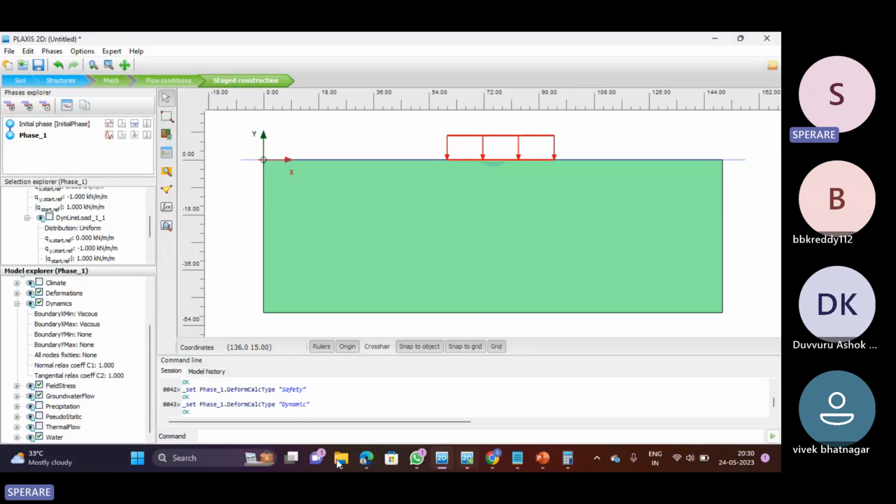If you go over here, in this particular image, because of the vibrations, a vibration is coming and hitting my Y minimum, and after hitting it, the vibration can reflect back. Why will it reflect back? It is not deforming this, because I already have a deformation restriction here. So in the boundary X minimum, it is already normally fixed, so there is no chance of deformation at all. So the vibration which is coming over here will hit and come back.